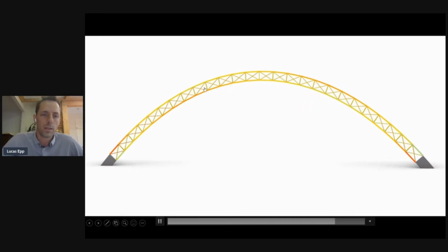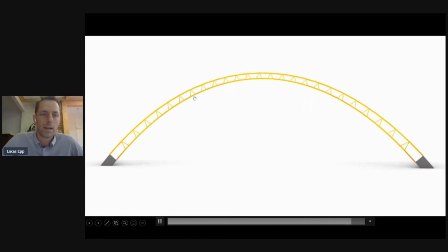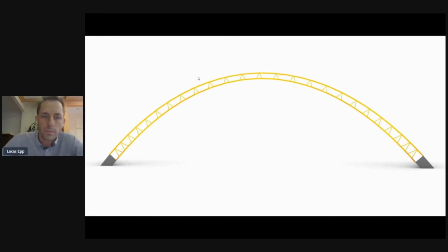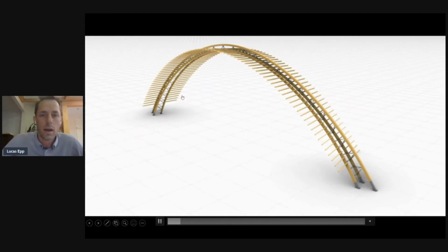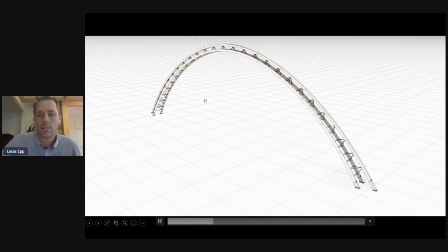The initial concept was using X cable bracing, but then we came up with a concept to change it to this splayed V bracing system, which is really interesting, and created this idea, which the architects were really interested in, of an ephemeral connection between the top chords of the truss and the bottom chords. You almost can't see them. These are just very thin steel plates. So it almost looks like the truss isn't a truss at all. That was a key structural concept.